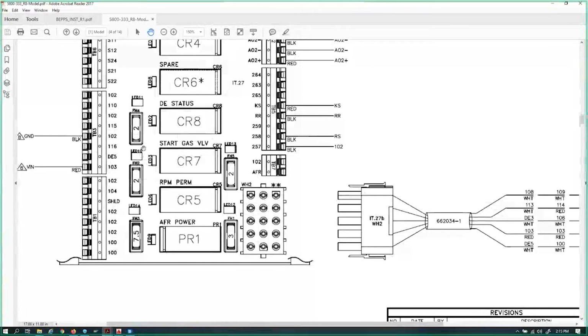And I said, well, hey, go find fuse 4. And I might give him a little pointer and tell him where it's at exactly. And he says, hey, man, there's a red LED on by that fuse. And I said, well, that means the fuse is blown. So each one of these fuses has a nice little red LED beside them that lights up when that fuse is blown.